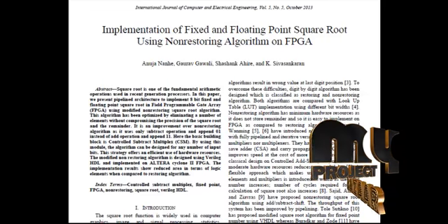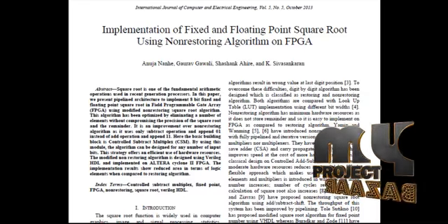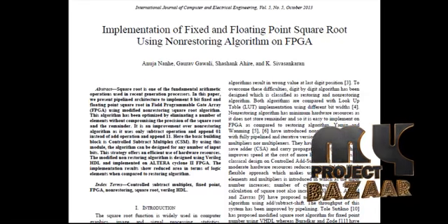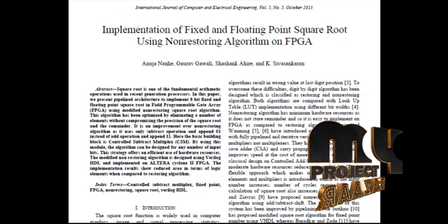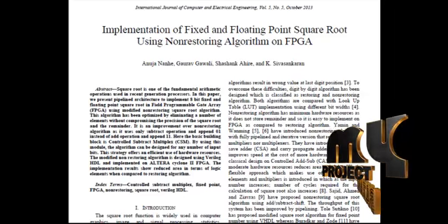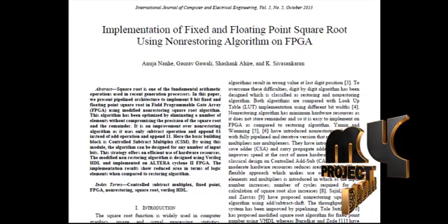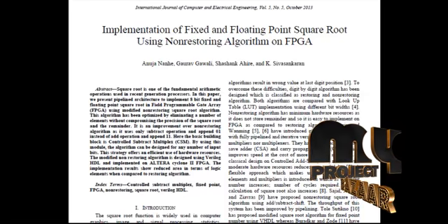In order to implement floating point reciprocal, division and square root components, there are three parts of the floating point number to consider, based on the previous introduction of floating point representation, which are the sign bit, exponent and mantissa. The computation of the sign bit and exponent depends on the operation and is straightforward. For reciprocal, the sign bit of the result is the same as that of the operand, and the exponent is the result of subtracting the operand exponent from 0.